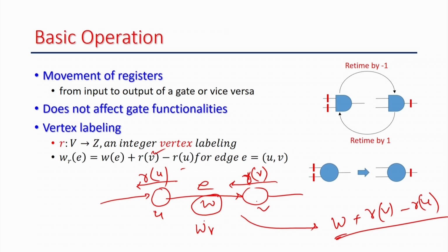So that will define your retiming, right. So this is something I discuss here. Retiming is about solving this problem: how to find out this R value for each node. What we are going to do is associate a vertex level R with each node, which will define the number of registers moved from the output side to the input side. So that is R v.